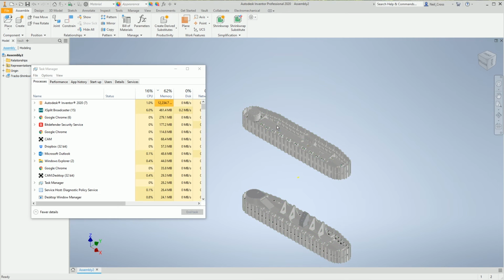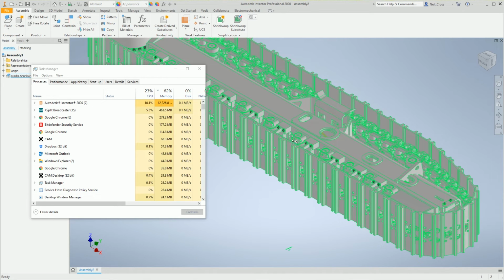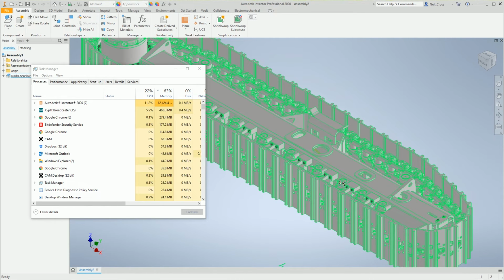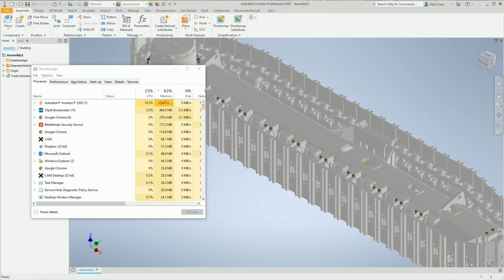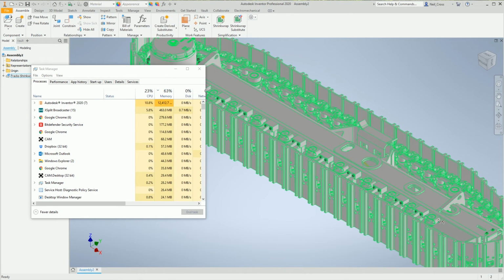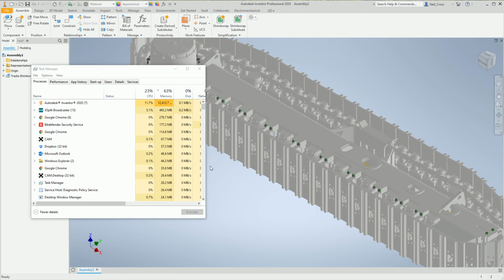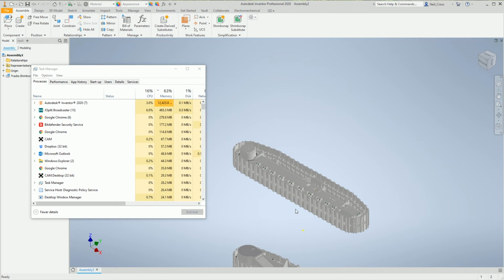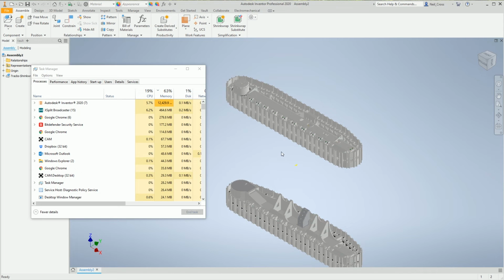So the solution to getting around this and to fixing this, mate, is if you need to create a shrink wrap of these tracks to use as reference, for example, I know there's very few people out there who'll use this, but it could be, thinking of your use case and what you would do. You might only need that hole there and maybe these holes here. All of this data here is completely pointless. It doesn't even need to be in the shrink wrap. So when you create your shrink wrap, exclude all of the parts that you don't need and only include the stuff that you do. And that seems like a pretty simple, straightforward solution. But if you didn't know there was a problem in the first place, you might not have considered that, and you might be ending up with issues like this.